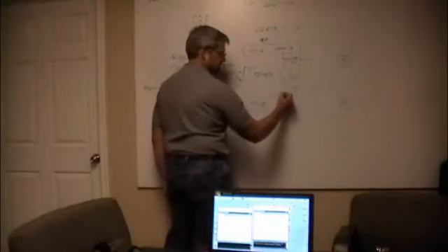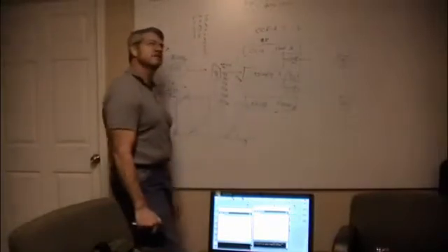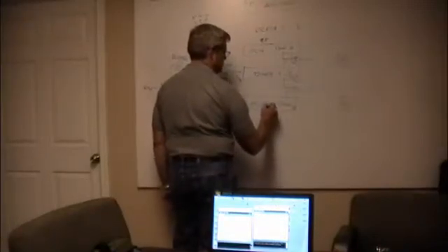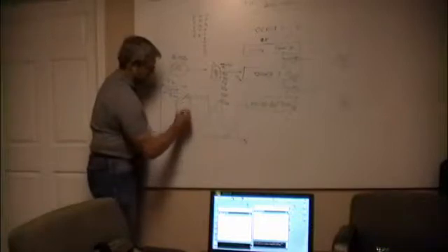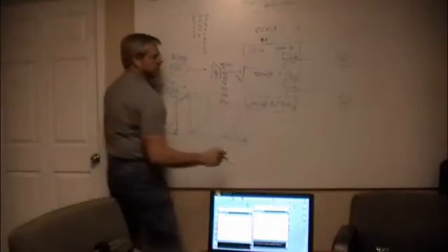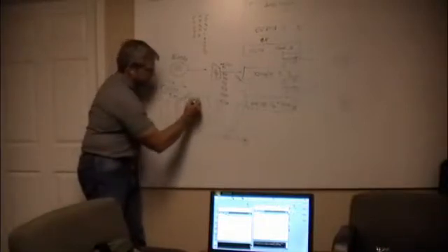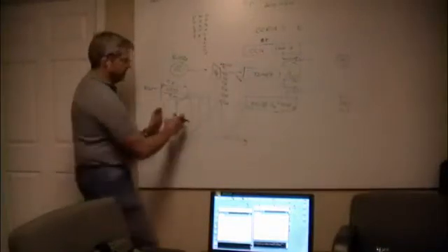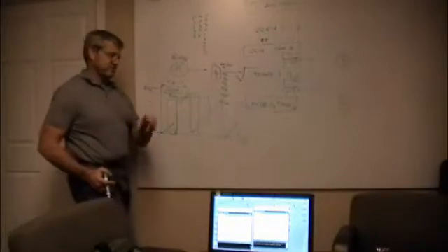And I can do that with both of these. So this one also has its AND, and so I can put a different one in here. Are those 16-bit registers on that one? I think they are. So let's make this one 16K. And so this one then will come here and it'll toggle, and it'll toggle, and it'll toggle. Or I can make it 2K, and it will come here and toggle there, and then it will toggle there. And you see what I'm doing? The frequency has stayed the same, but I'm changing its position in space when things happen. Not something that you would normally do, but it's there for you to be able to do if you want to.